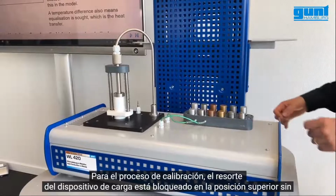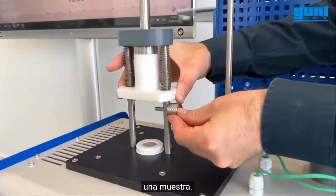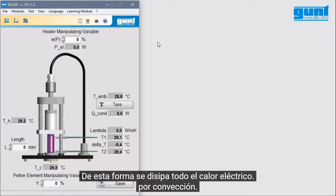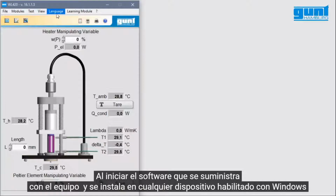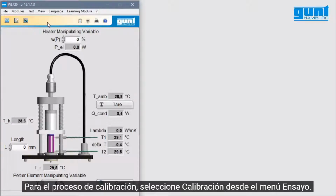For the calibration process, the spring-loaded device is locked in the upper position without a specimen. This way, all the electrical heat is dissipated via convection. When starting up the software which is supplied with a unit and installed on any Windows-enabled device, you can select one of 4 languages. For the calibration process, you select calibration from the test menu.